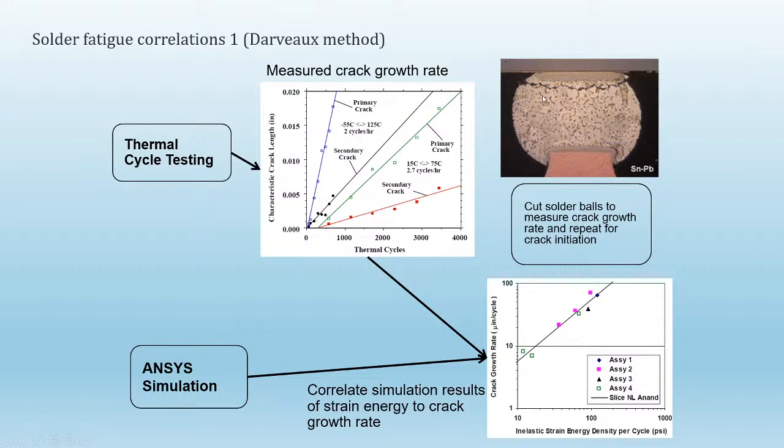And I've talked to people that want to know what happens if the crack grows in the middle of the solder, near the top interface, near the bottom interface. We can handle all of that with fracture mechanics, and I think it's a great method. I haven't seen a lot of papers to establish the type of correlation needed, but I think it's definitely a very promising area to look into, because I'm sure you can find correlations like this using the fracture mechanics methods as well.